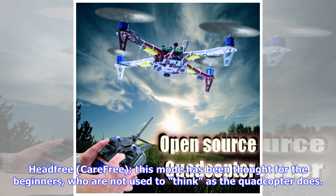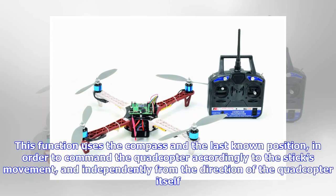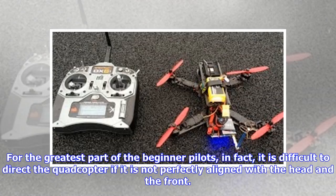Head-free, carefree. This mode has been thought for the beginners, who are not used to think as the quadcopter does. This function uses the compass and the last known position, in order to command the quadcopter according to the stick's movement, and independently from the direction of the quadcopter itself. For the greatest part of the beginner pilots, in fact, it is difficult to direct the quadcopter if it is not perfectly aligned with the head and the front.